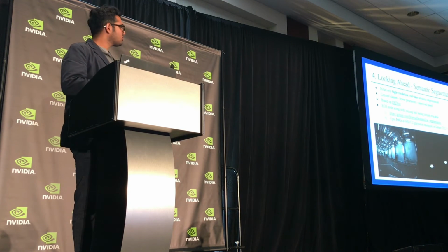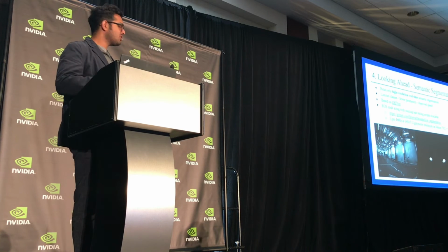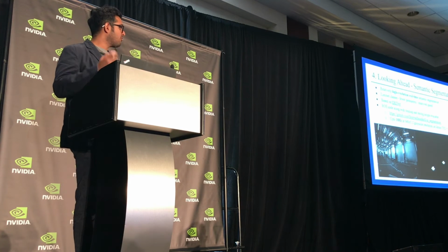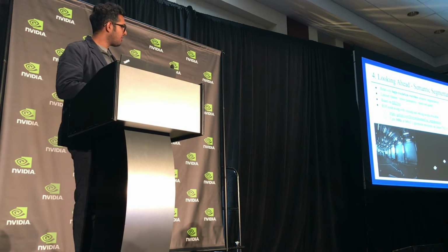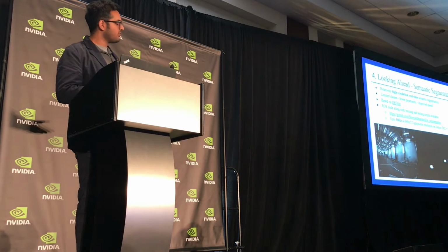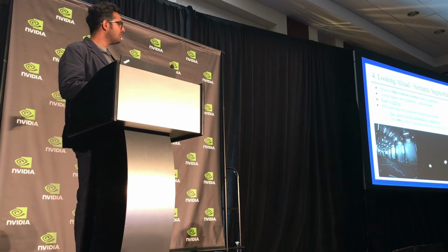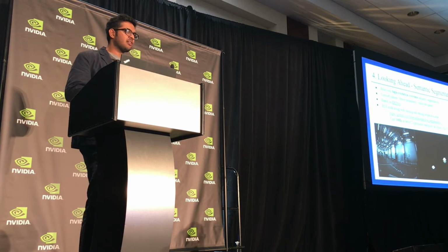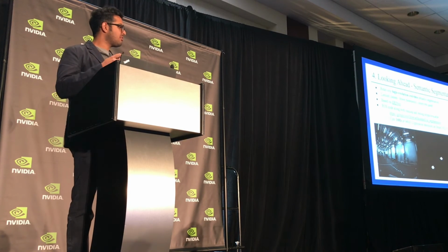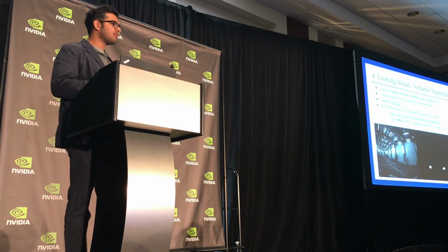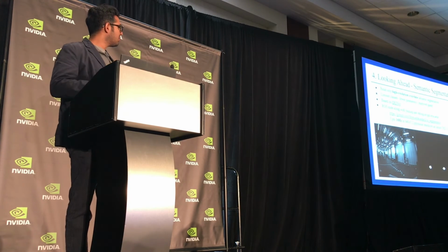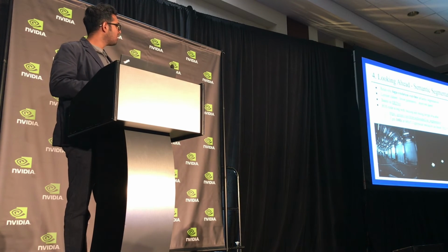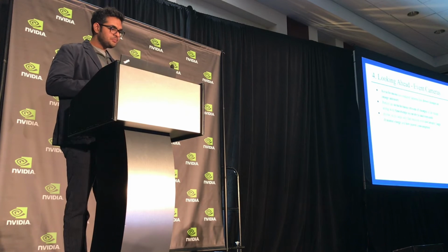And on the right, we've also experimented with indoor semantic segmentation, so for our UAV to figure out what's what inside an office space. This is actually some of our classroom spaces. So it detects the floor as the yellow color, and the green is a door, and the ceiling in pink, and the walls in red. So it's very coarse right now. What we can do in real time isn't the state of the art in segmentation in the deep learning world, but we can get some of these really sophisticated networks to work in real time on our UAV platforms.